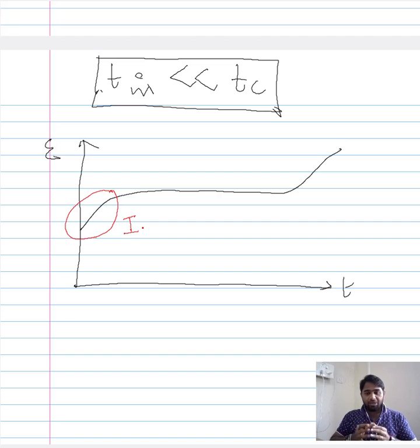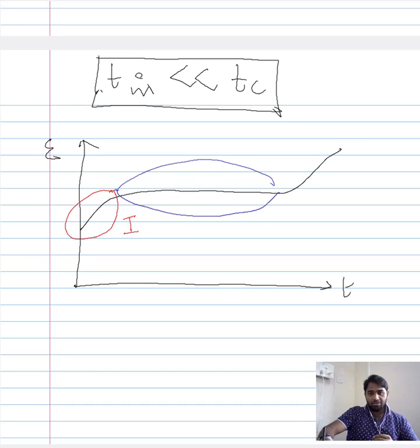When the time taken for the instantaneous creep is insignificant when compared to the overall creep period, then your curve begins with the transient region. Then stage 1 exclusively characterizes the transient creep, and the other creep regions will not change. The steady state, that is stage 2 of the creep, will be the same, and similarly stage 3, the accelerating or tertiary creep, will be the same. However, one factor that changes is stage 1 of the creep.